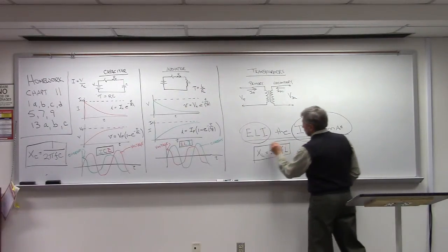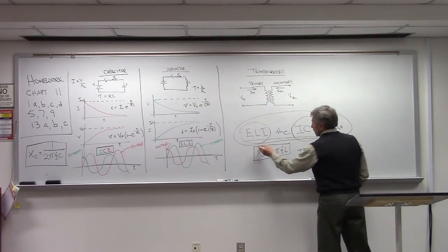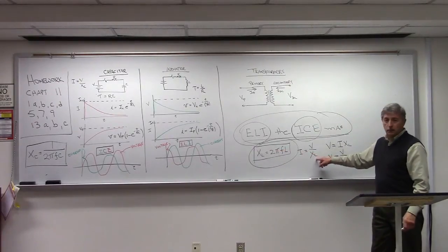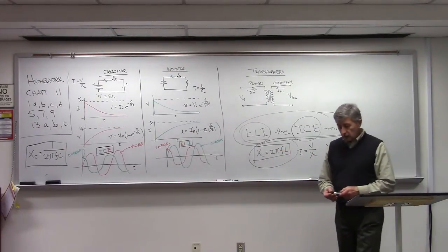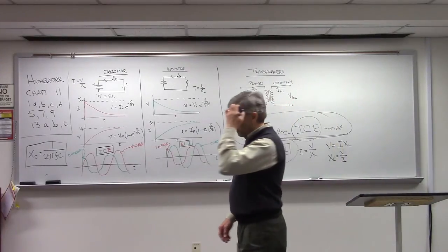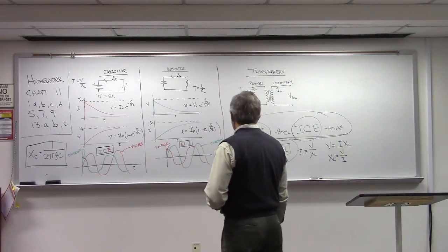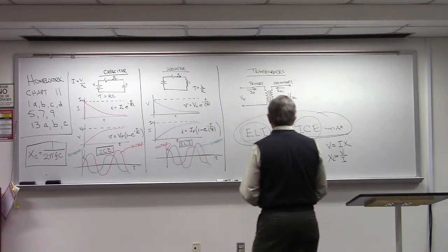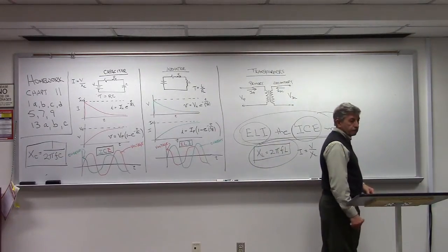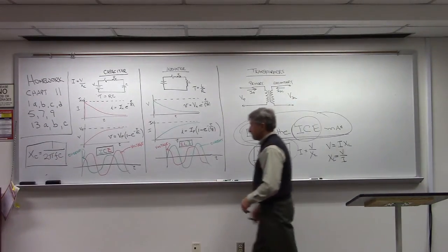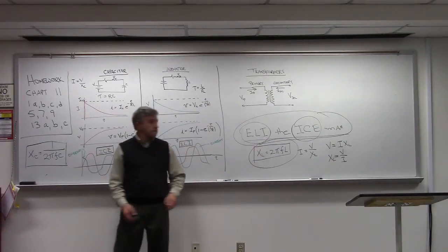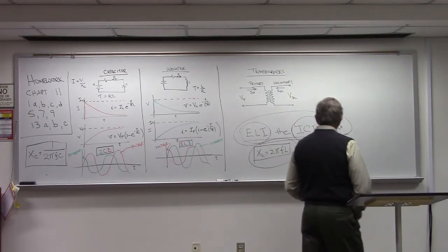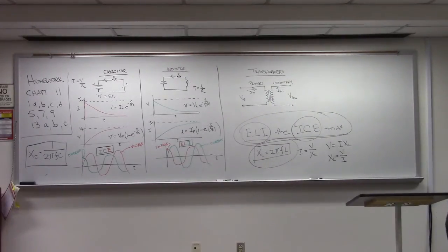This guy right here, ELI the ICEman, and this. Once you know that, you can just use Ohm's law by putting in your XL in place of resistance. Probably should take a picture of that, it's kind of messy.